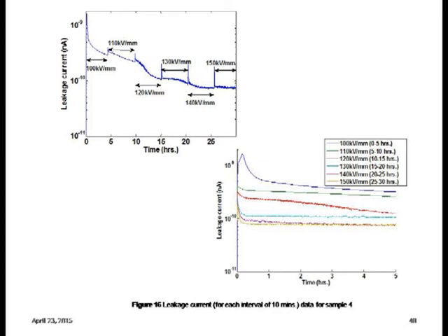The previous test is for just 30 minutes. This test, we have conducted for 30 hours. You see clearly even after 30 hours the leakage current is not getting saturated. So it is a very, very important consideration, because normally in insulation other than polymer insulation it saturates within a few hours, right? But low density polyethylene is a very good insulation, it has high breakdown strength, and it can be easily manufactured, and cables or whatever shape you can make very easily.